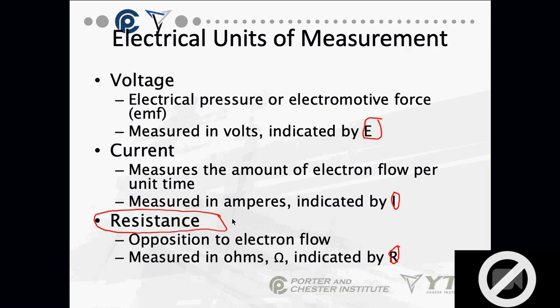And I can promise you there's a question on that on your final exam. Okay, that's going to try to get you to say you can put an ohm meter on an energized circuit. No, you cannot take a resistance reading on an energized circuit. Your meter will melt down. It will blow the circuit boards inside if the voltage is high enough. Don't do it.